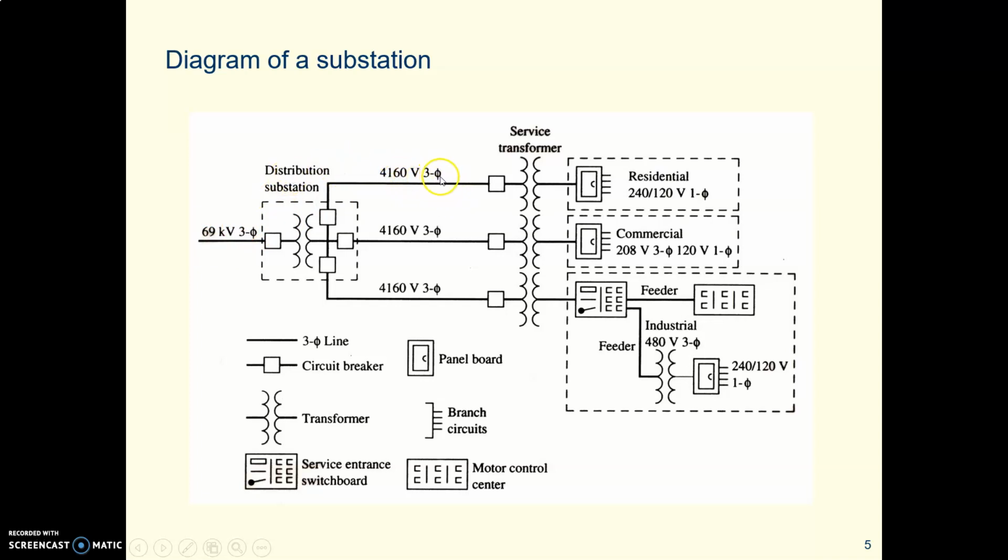This symbol right here that looks a little like a diameter symbol, but it has a little line straight up and down, that's the Greek letter phi, P-H-I, and that symbol stands for phase. So this is saying these are three-phase lines. Here's a residential line, which we've seen comes in at 240. Down here is an industrial or commercial line, which comes in at 480.